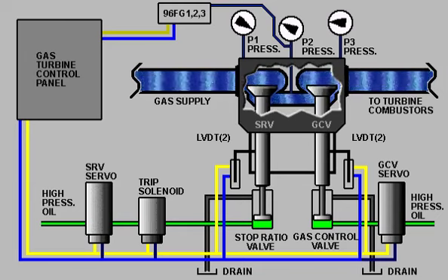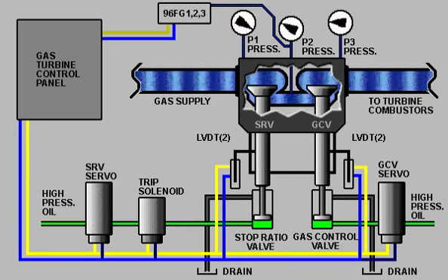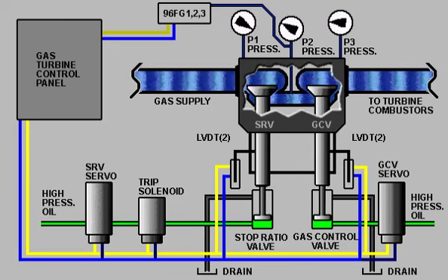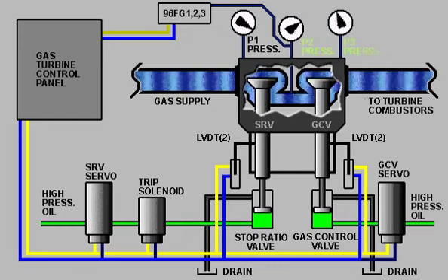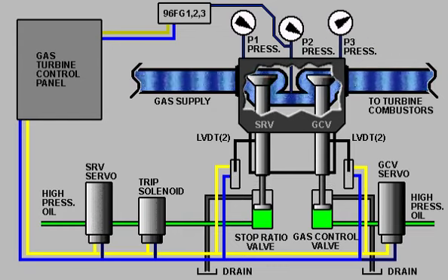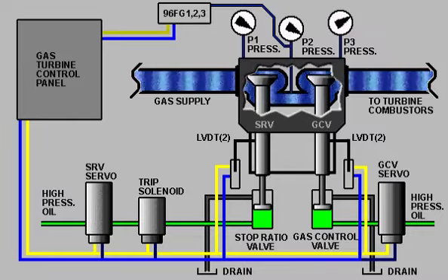As turbine shaft speed increases, the servos continue to receive signals to send more hydraulic oil to the valve cylinders, opening each valve and increasing the P2 and P3 pressure. The control and feedback signals continuously adjust each valve as required by the control system.